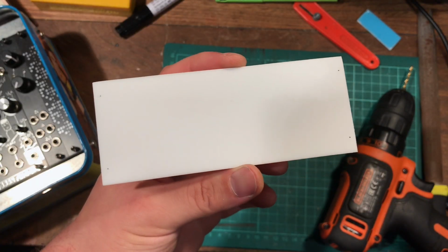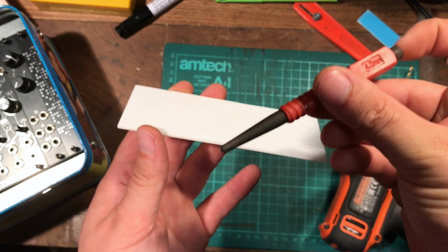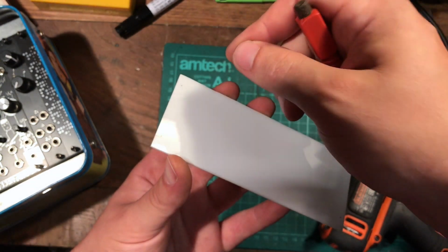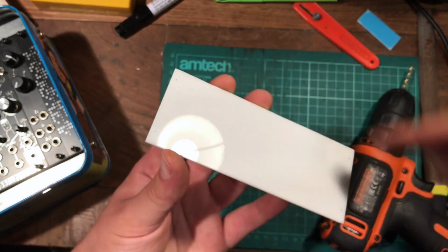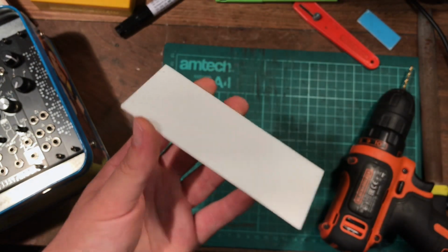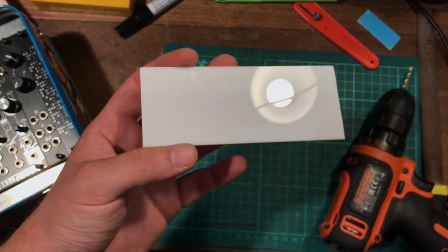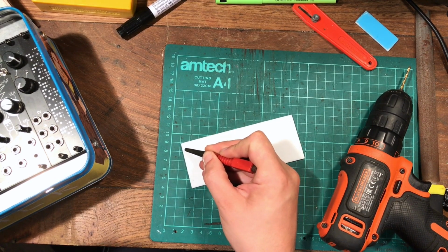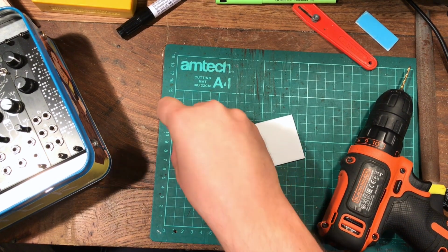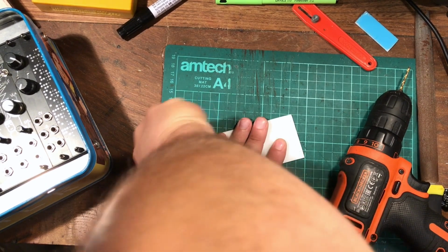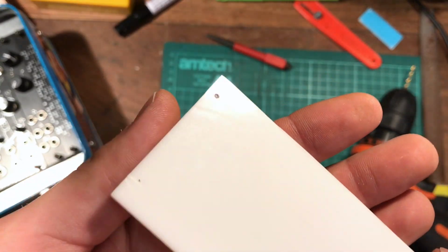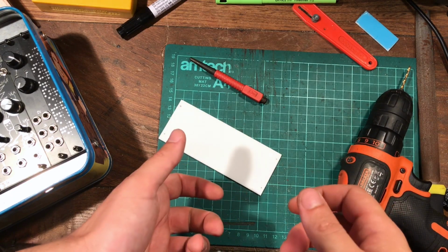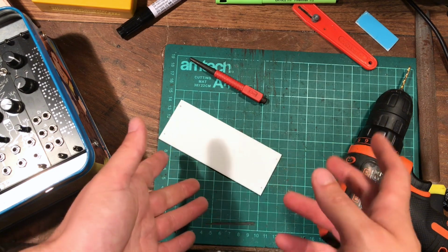So you'd think the next step would be to just drill the holes, but what you really want to do is use one of these punches here to make a little divot in there, just so it holds the end of the drill bit, stops it wandering off and scratching all your panel. Trust me, that's not fun at this point when you've gone through all the trouble to do all the filing. So you just put it down on the surface, make sure the point of your punch is right on the mark, and then just drive it on down, twist it a bit around just to make a little indent. Don't hammer it down like you might do with some metal, because it might just shatter the acrylic.